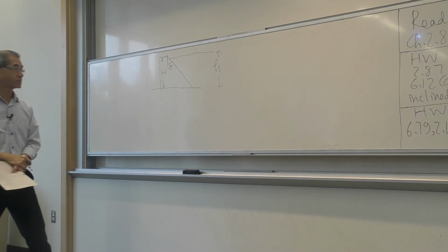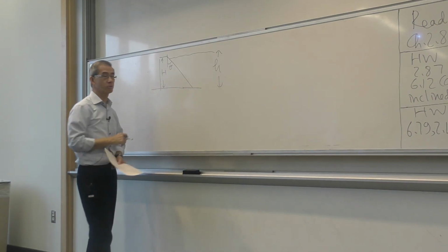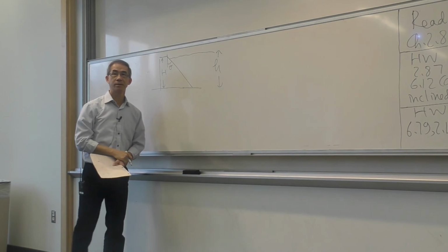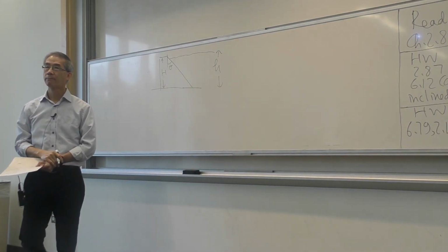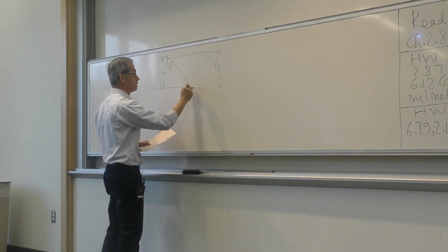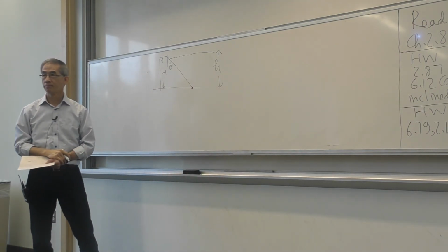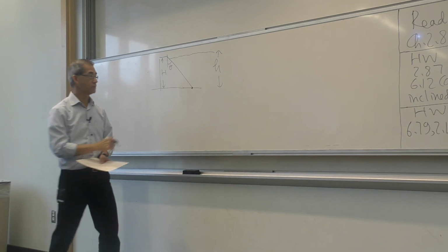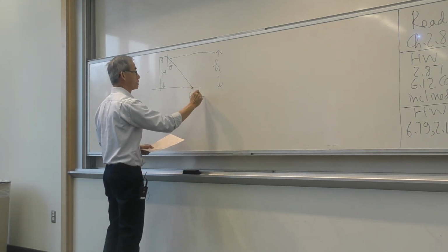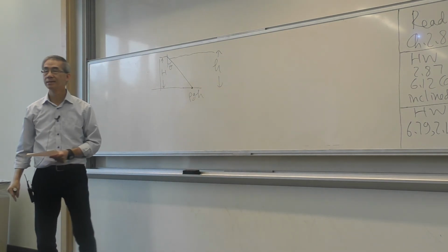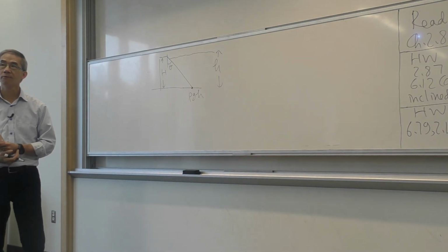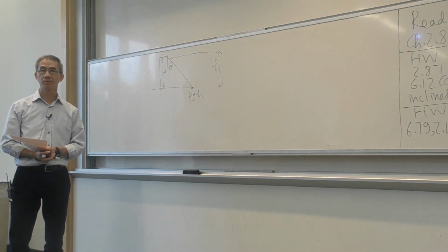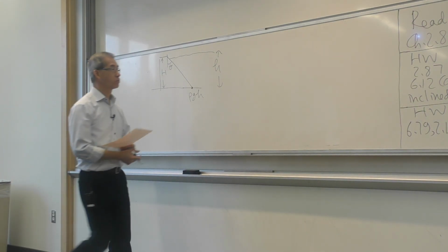Now with this caveat, can you tell me and draw the pressure prism on the right side, the wetter side of this dam? What is the pressure at the base again? What is the pressure at the base? Very good, rho GH. Nothing to do with an angle theta, because it's all dictated by the vertical height from the free surface. So it's still rho GH. What would that pressure prism look like? Let me remind you. Pressure